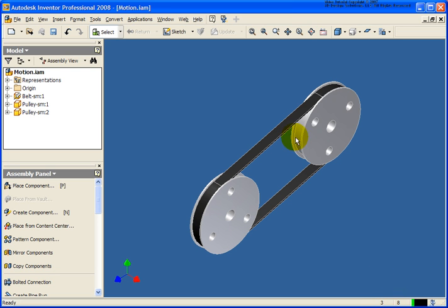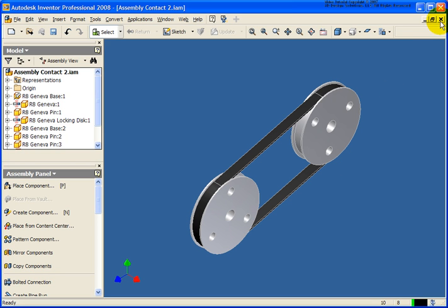So in this file, I have 3 unique components, hence the number 3. And you'll see in this case, it's at the number 8 because we had 5 components from the last assembly, and it's 3 components in this assembly. So as you can see, the number of components are being added from window to window. So if you have 10, 15 windows open, each of those are going to be taking memory. So only keep the files open that you're going to be working with.